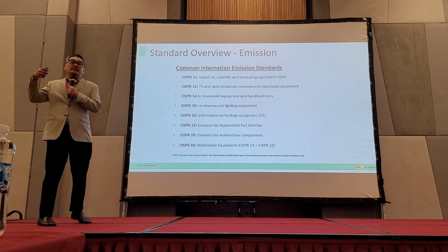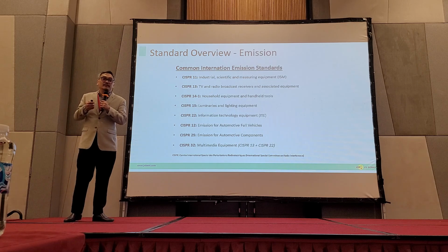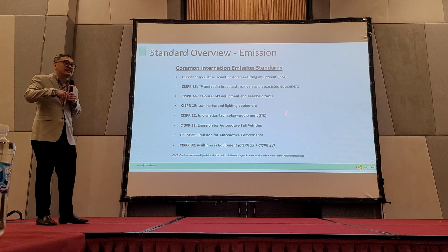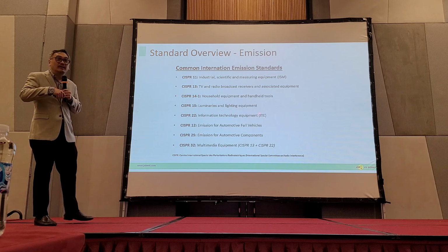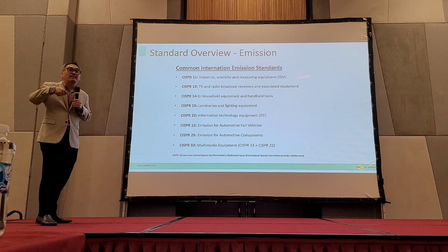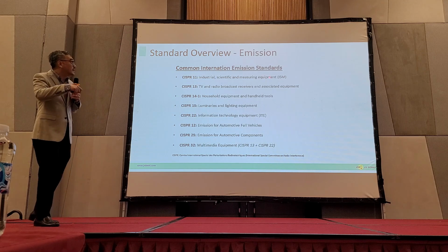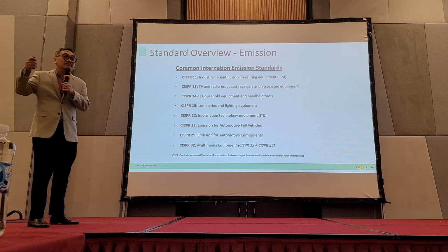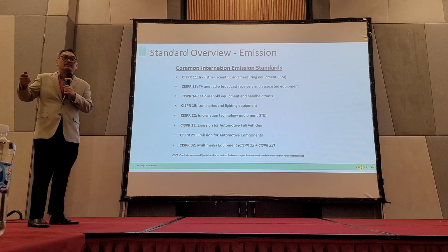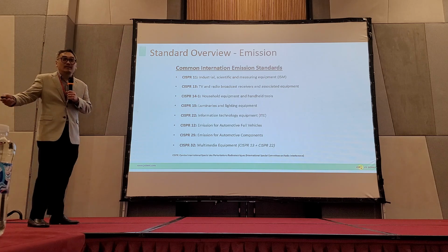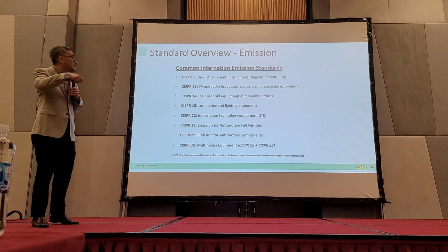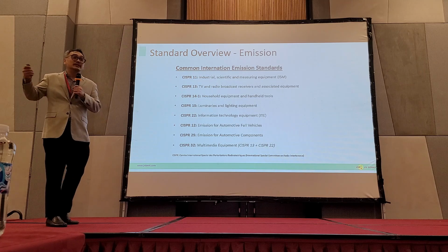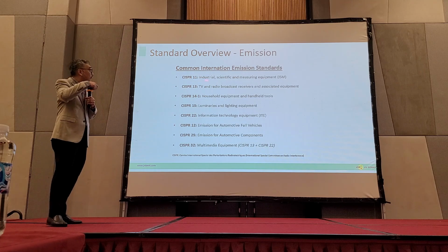When we talk about testing EMC, it's always about what standard we test to. These are some of the typical, common EMC standards available. Of course, there are many more standards. For example, what kind of products are you making? If you are making industrial scientific measuring equipment, ISM, for example a Keysight spectrum analyzer, it is not a household equipment. You don't use it at home. It's categorized under industrial and scientific measuring equipment. So the Keysight spectrum analyzer needs to do EMC tests itself, and they need to comply with CISPR 11.